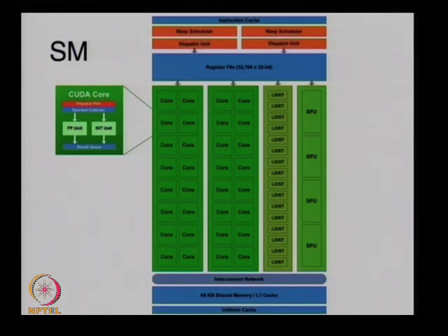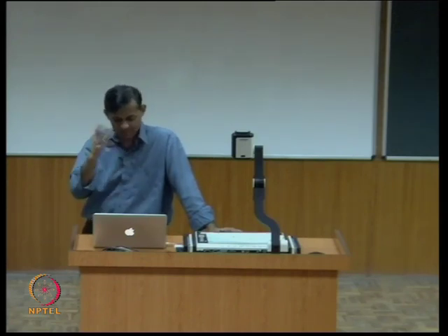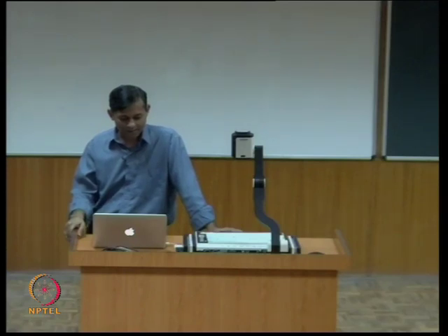In Fermi, there is 64 kilobytes of local space, the scratch space, which was 16 kilobytes in the machines you will be using. Fermi also can partition that into a cache and a scratch, which is directly user controlled. So you decide what lives in that cache rather than some predetermined cache replacement policy. And then there is L2 and all that.